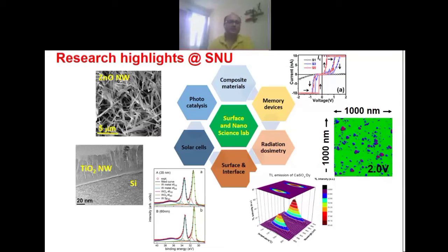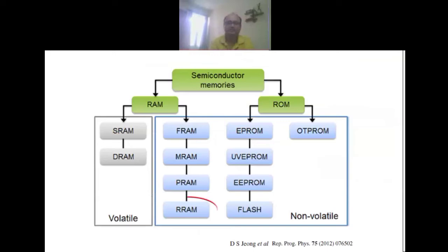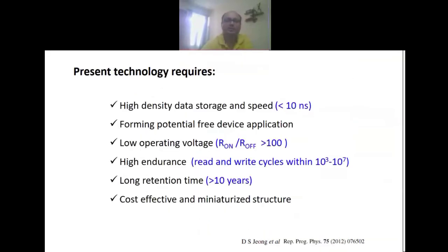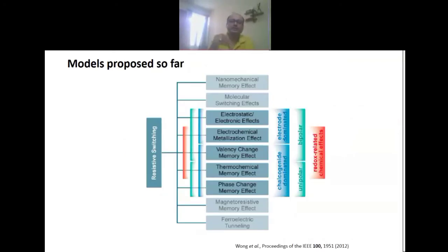Here you can see that in both cases, in the valence band, there are two different levels which connect at the valence maxima. The only difference is that the slopes are different, and these slopes are a very important factor. They help us understand the effective mass of the holes. The electrons are populated up here, and whenever you eject one electron to populate the conduction band, you create holes in the valence band.